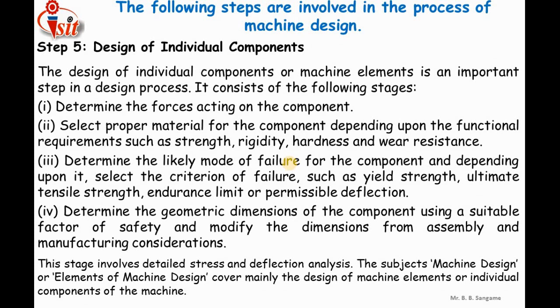So according to the working condition, the type of load, the loss of life and loss of property, many factors need to be considered while selecting the factor of safety, and according to that the dimensions should be modified. At this stage detailed stress and deflection analysis is done for the individual component.